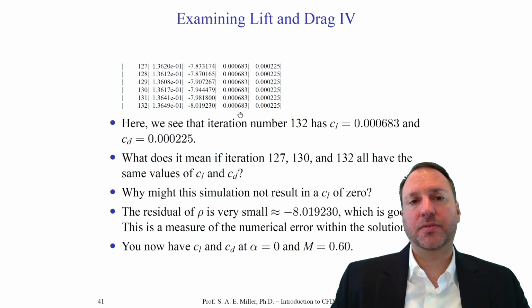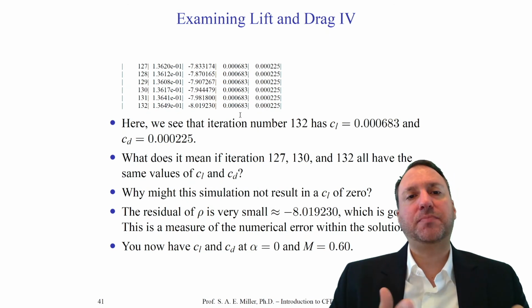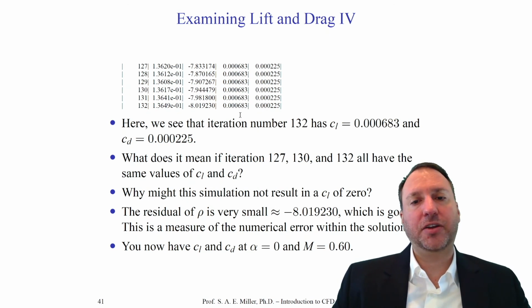So now we found, with a simple rerun of the code, changing two lines in the configuration file, the angle of attack and Mach number, the new coefficient of drag. You can experiment with this. Change the Mach number to any value you want, 0.2, 0.5, 1.5. See what happens. In some cases, your solver will crash. In some, it will, of course, converge.